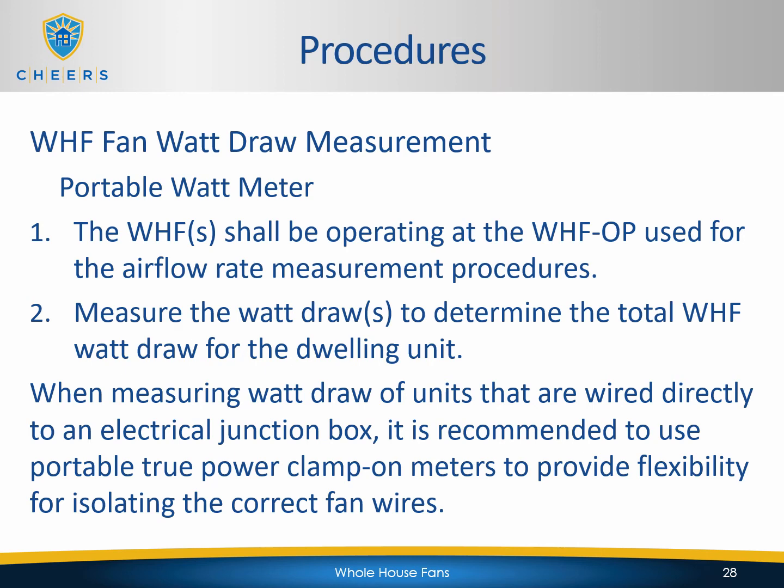So you're going to do all that setup to do your airflows, and then before you shut everything off, you're going to go and measure the fan watt draw under those same conditions, the same -10 pascals with respect to the outside. You'll then measure the watt draw or draws to determine the total whole house fan watt draw for the dwelling unit. Now with these portable watt meters, it all depends on how these things are set up. Most of them are going to be hardwired. Some of them may be plug-in, but you're going to have to figure out which ones they are.